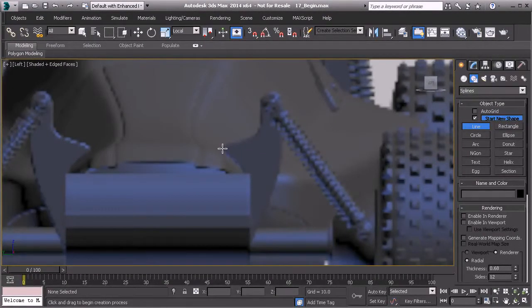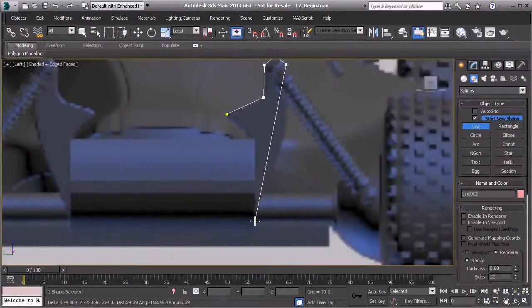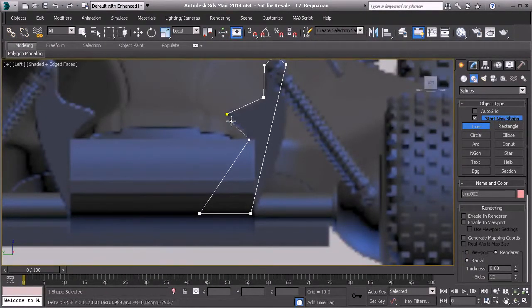So starting right here, I'm going to left click and create a point. And let's go to about midway in this line here. And I'm going to create three going around the top. So one on this side, one at the topmost part, and then off to the right. And let's come all the way down here to this point on our connector. Now this looks to be like we're cutting off that entire curve, but what we're going to do is change our tangent types of our vertices and get that shape. So I'm going to left click out here, and then we'll go up to this point here and then end here.